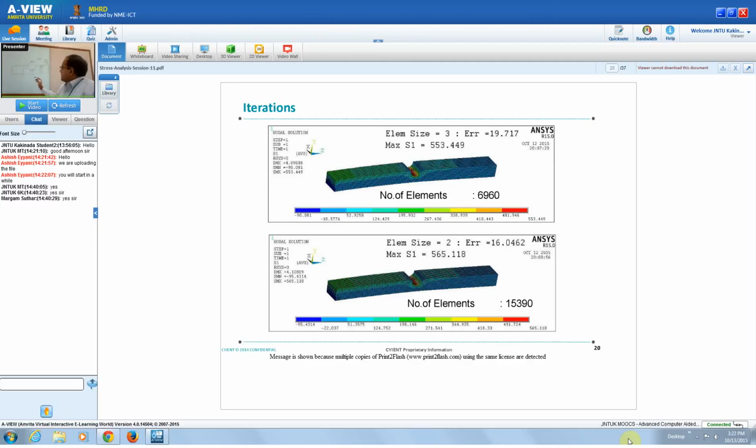So that will reduce the element count. With uniform mesh, we get 41,000 something elements. With this type of mesh we can reduce it to 25,000 also. So this is how we need to follow our finite element modeling strategy to achieve convergence.